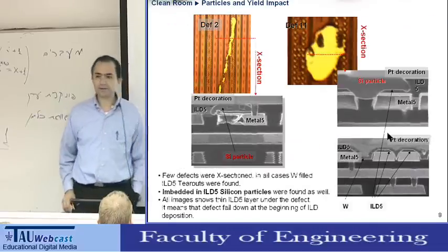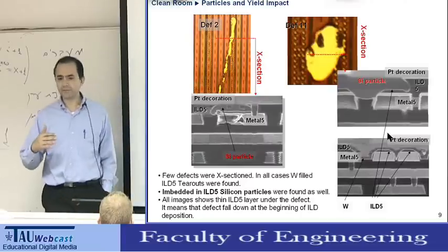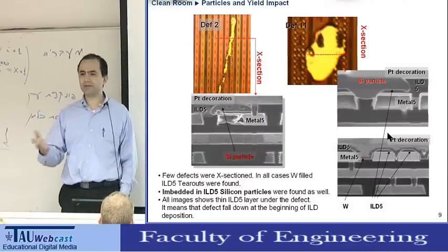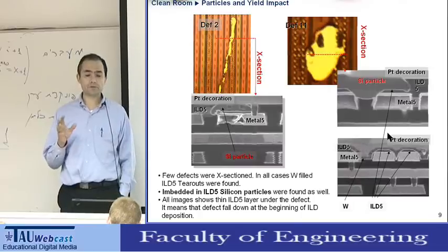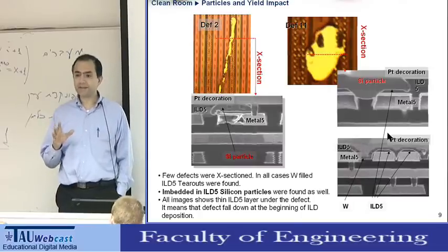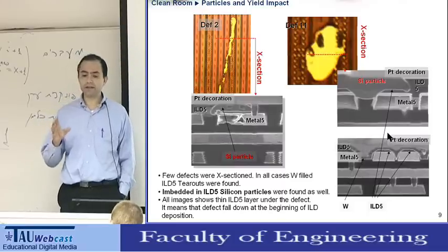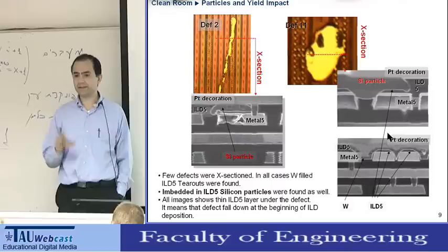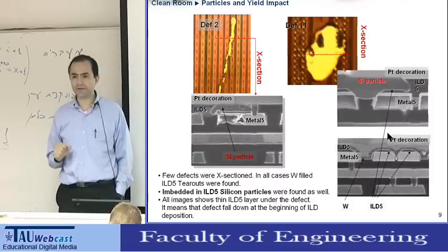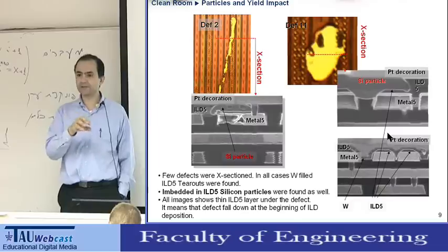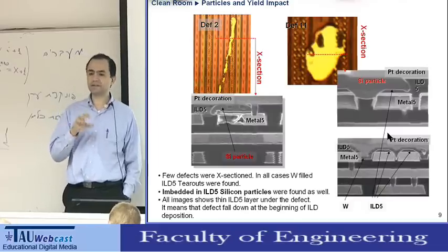Other kinds of... It's not done randomly. There is an order, and it's being optimized depending on the process, on the wafer, usually. So it can be done for all the dies in the wafer. That's usually the case. But even in a die, we don't check all the area in the die. For example, sometimes we look in the memory areas. Sometimes we look in some other sensitive areas, which are more dense. We're looking for the particles in certain areas.